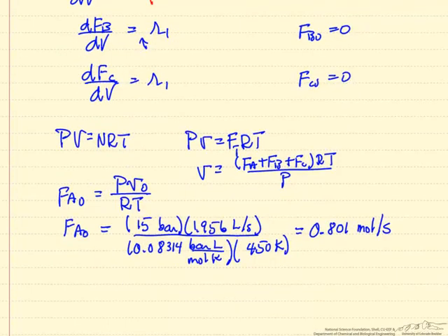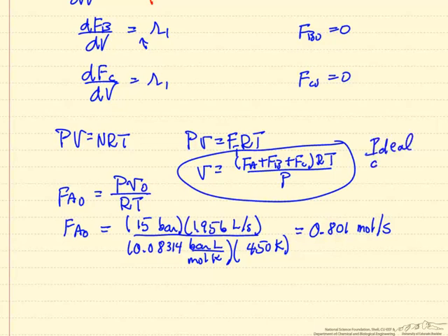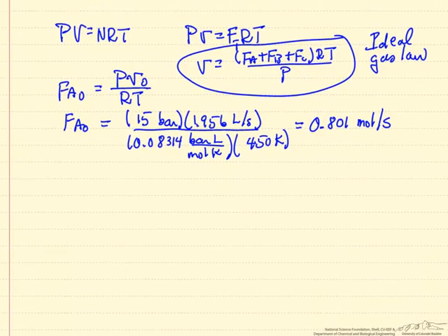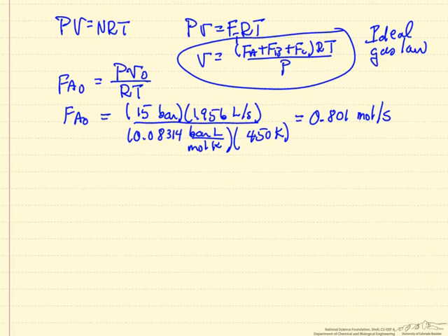And then we're going to use this equation, which remember is essentially the ideal gas law, in solving to account for the volumetric flow rate change as you move down the reactor. So we have the mass balances. We now need the energy balance.